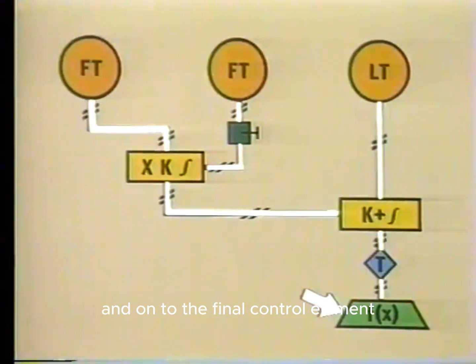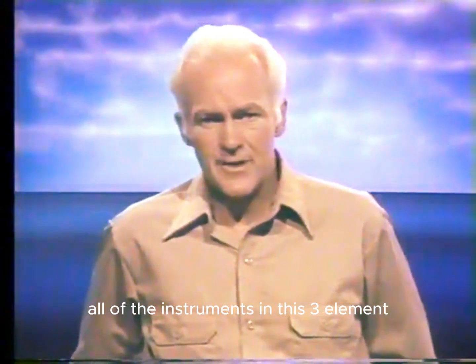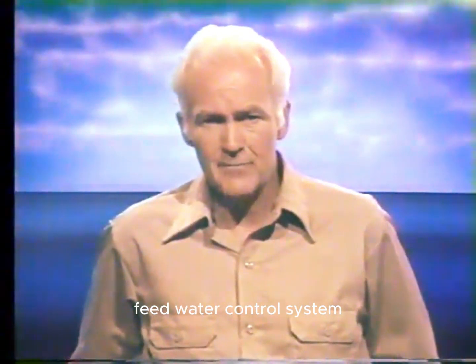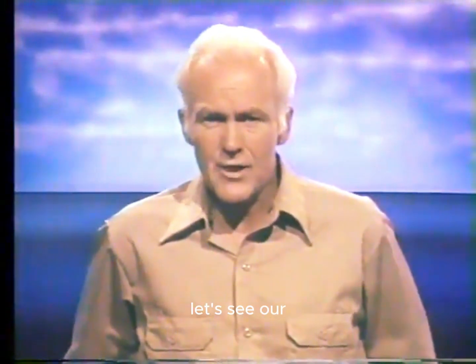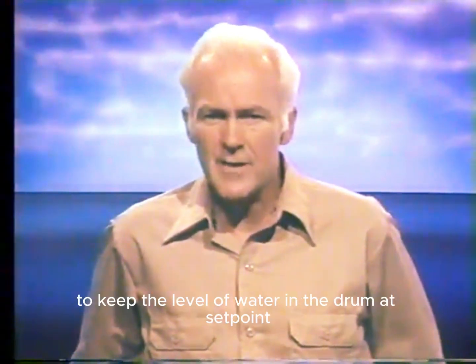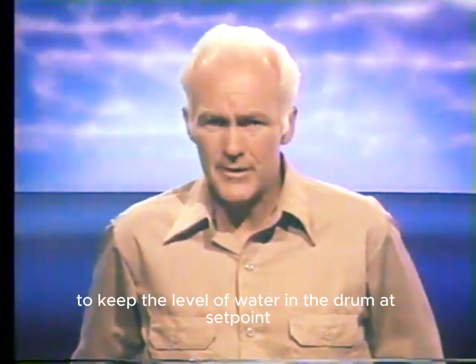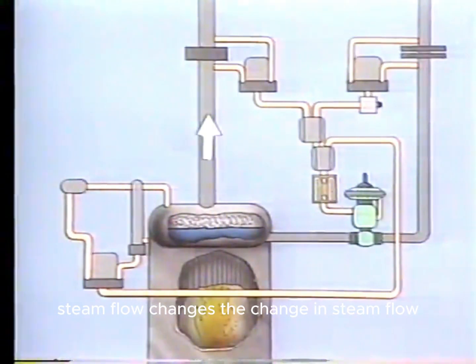final control element. Now that we have identified all of the instruments in this three-element feed water control system and identified their function on a logic diagram, let's see how a change in demand for steam affects the control system and how it reacts to keep the level of water in the drum at set point. When the demand for steam changes, steam flow changes.